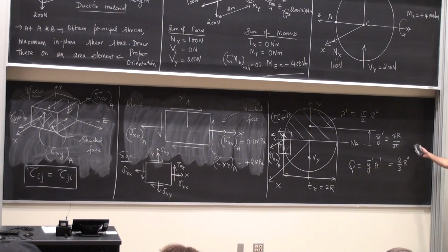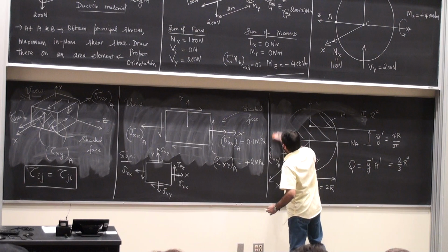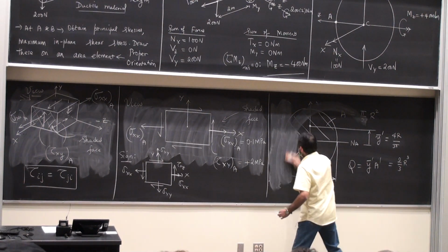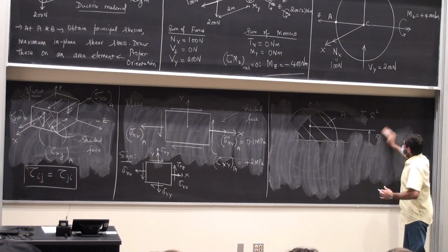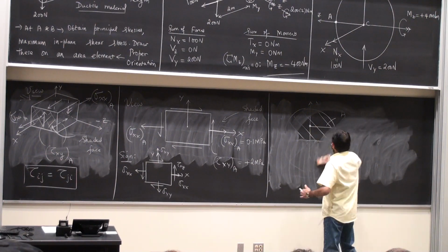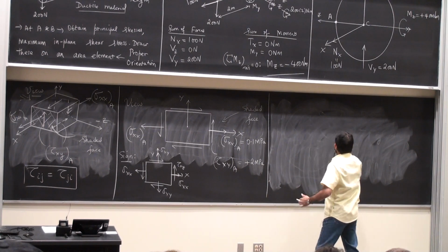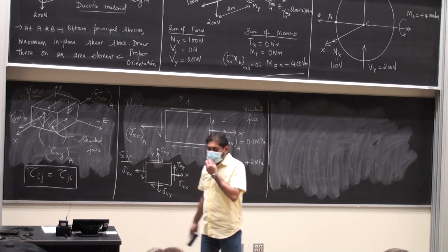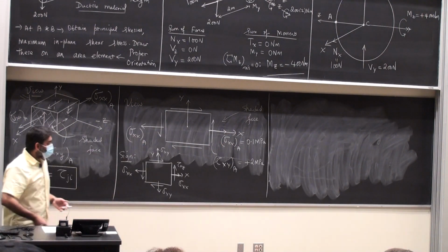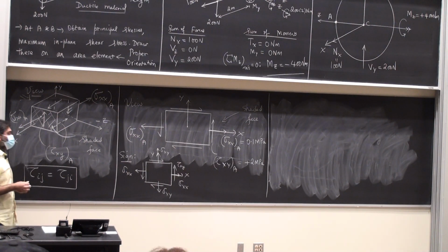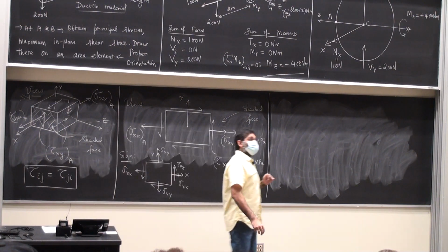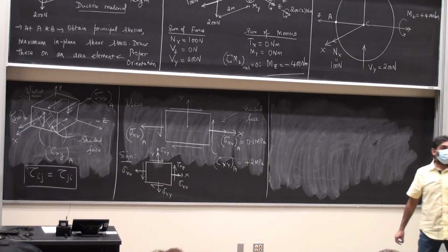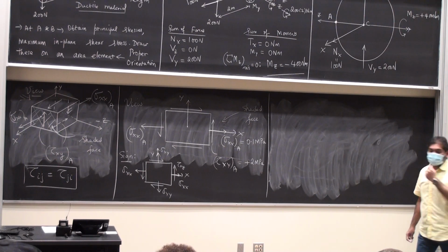Alright, I'm going to get rid of this figure here so that we end up drawing a Mohr circle. I want to do it at point A. We'll complete it today. We'll come back and polish off point B on Monday. And I'll continue solving problems of this nature and introduce you to the strains in 3D as well on Monday. Okay. Why do I need to draw the Mohr circle? I need to figure out the principal stresses and the maximum in-plane shear stress at point A.